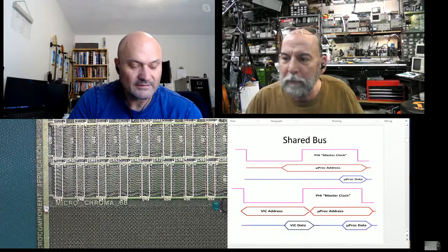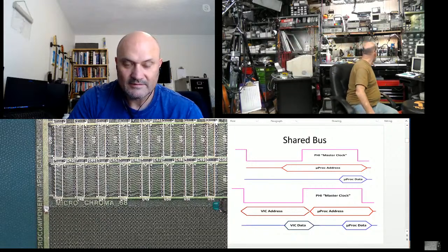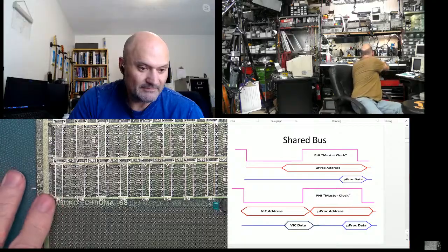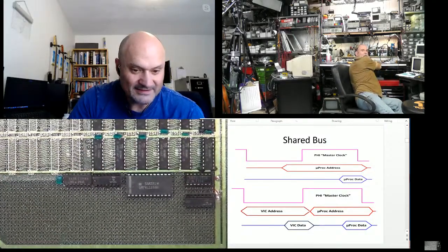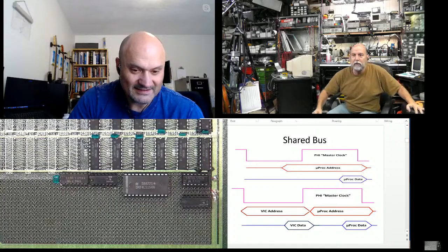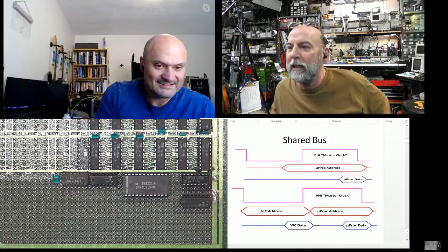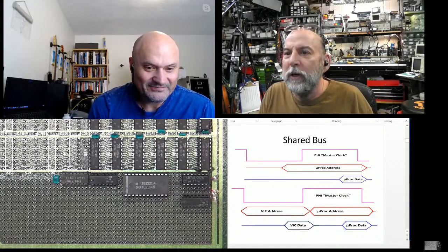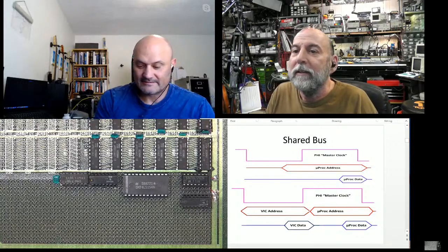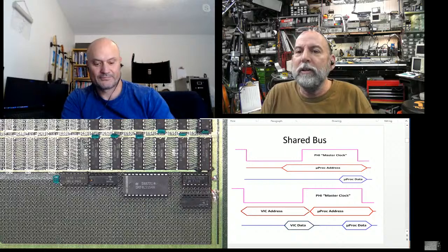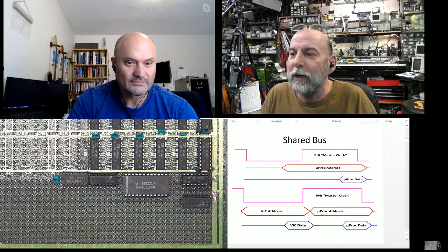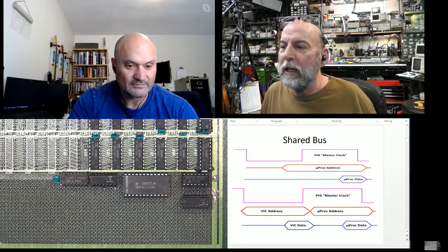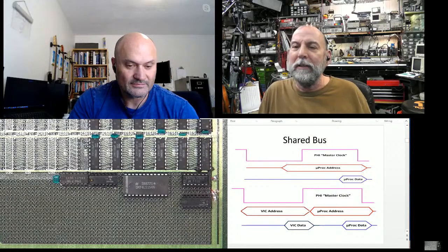So now what I love about it is this breadboard area is so typical of the 80s. See if I can get the prototyping area. And I used it. And you could see, so 74 LS154, we were talking about that before the show. If people have heard of the LS138, a real common 3 to 8 decoder, there was the LS139, which was a dual 2 to 4 decoder. Well, these are their bigger cousins, that 24-pin chip you see there. That's the 74 LS154. That's a 4 to 16-bit decoder.